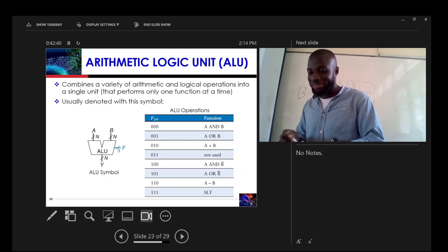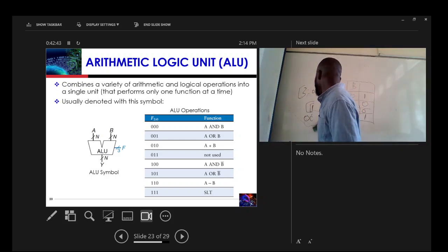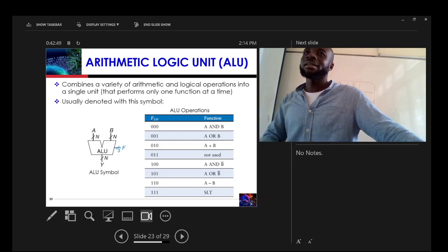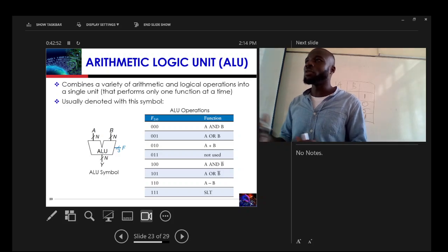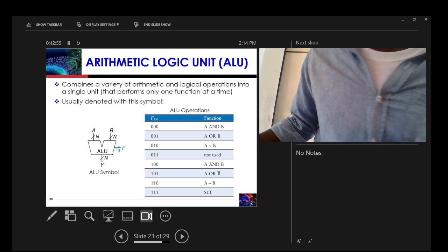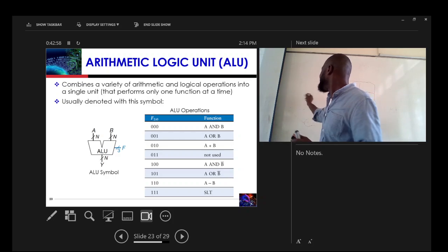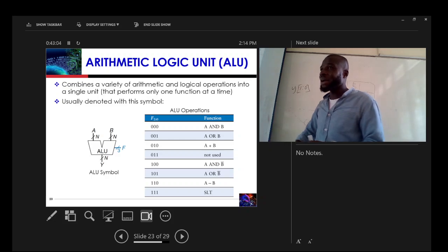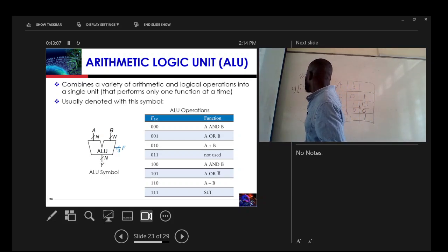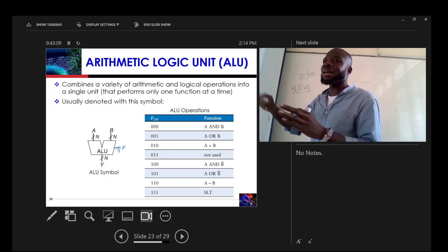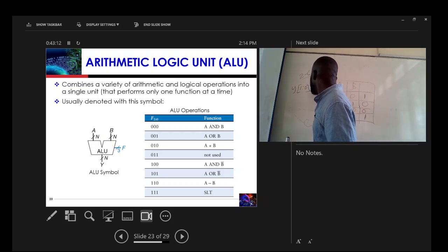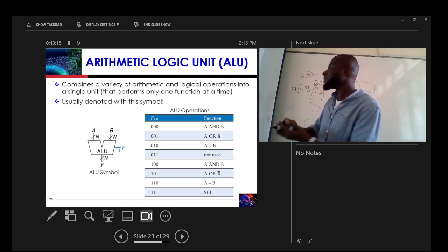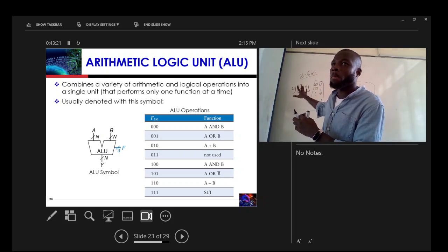And I thought you guys understood this already. This is mostly used in coding, like in Verilog or VHDL. If you code, you are normally looking at registers or buses or variables. So if you say Y and then 1 to 0, this just means 2 bits. I can address 0, 0, 0, 1, 1, 0, and 1, 1. So I can have 4 locations within those 2 bits.